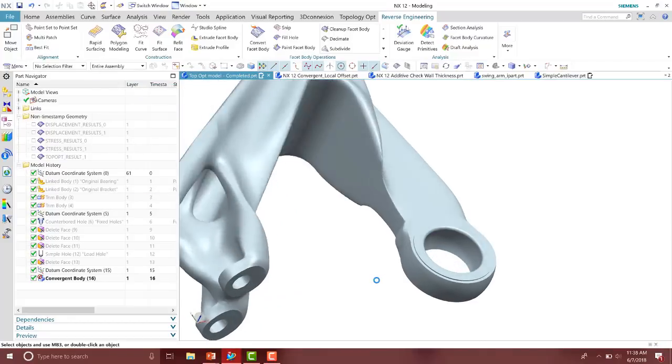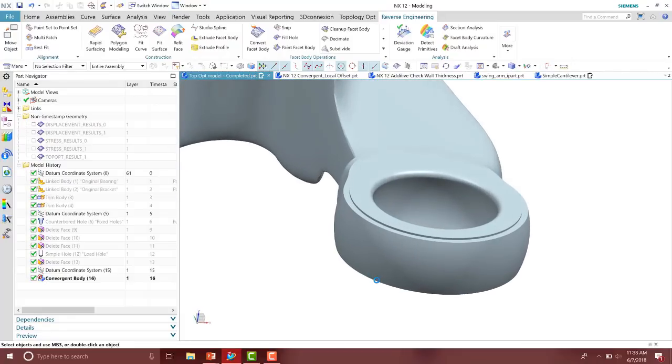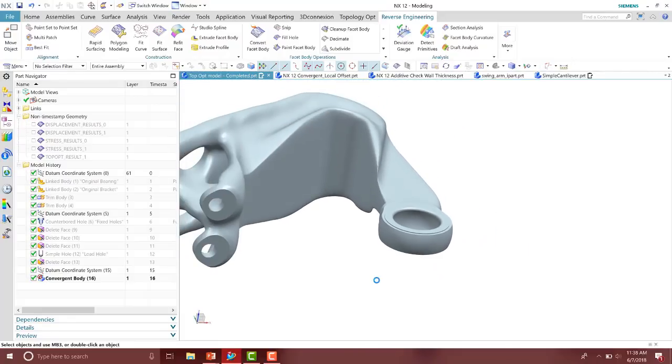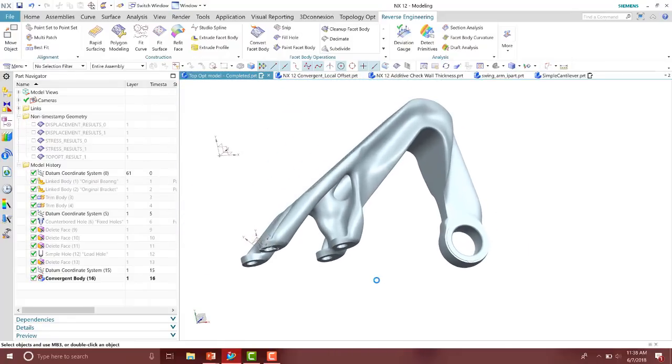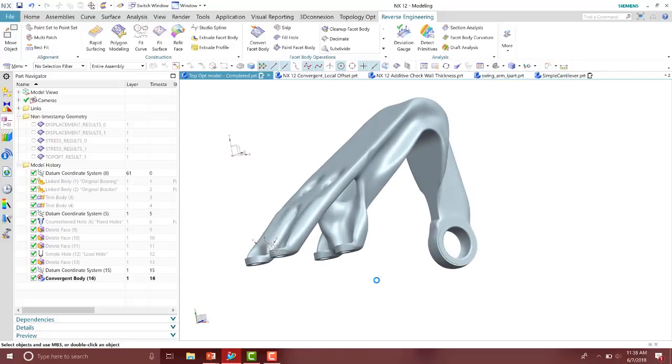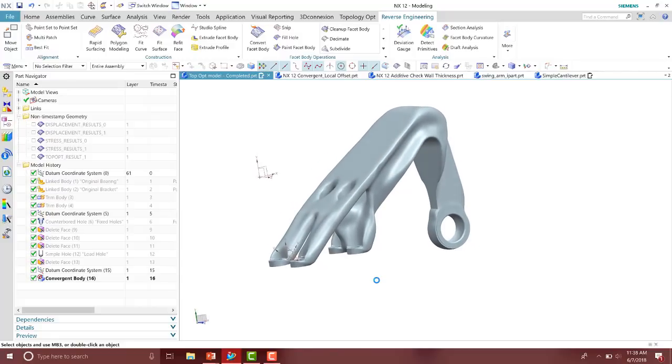So notice we used a create transition. We did an edge blend on a facet body. The reason we did a merge facets as well is that it could cause problems later with editing. Obviously we got an error there, and it could also cause problems later on when we 3D print the parts. You know, separate facets, it's separate bodies in there. So maybe we need to look at a tool to validate that our facet is good enough or it meets the requirements to 3D print.